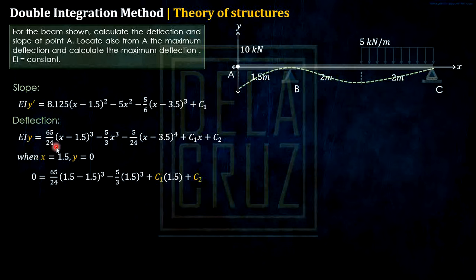If we substitute our x here, it will just be 0. Here, that will be 5.5. But if we substitute it in this term, this moment arm will be negative. When the moment arm is negative, we no longer include it. That is why I did not include it in the equation. Take note of that. Write it in your notes so you don't get confused or forget.